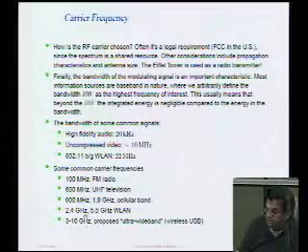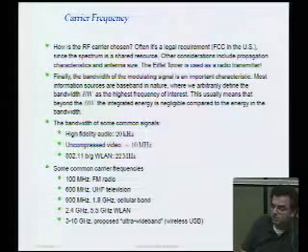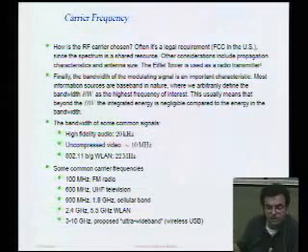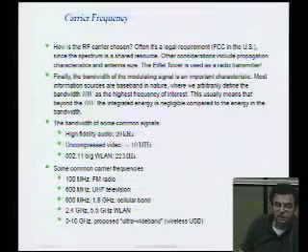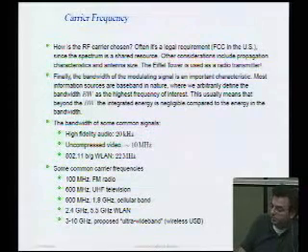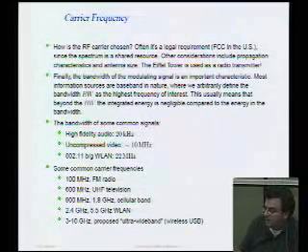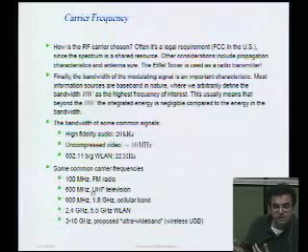And these days, actually, there's a whole flurry of activity in using spectrum in different ways, mostly for data applications. For instance, 3 to 10 gigahertz has been proposed as the ultra-wideband. Ultra-wideband because it's so much bandwidth. It's 7 gigahertz of bandwidth. Don't get too excited, though, because the amount of power you can transmit in that bandwidth is only about a milliwatt. But people envision this as a very short-range, high-speed link. Let's say like your USB cable without the cable, or wireless USB. So there's lots of spectrum out there, and it's being used in new ways.